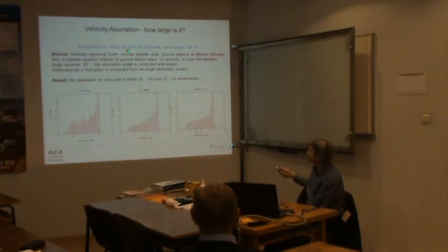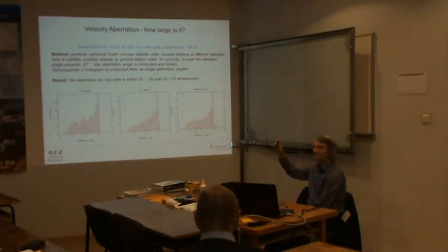We assume an orbit of a typical remote sensing satellite, 620 kilometers, with an inclination bigger than 90 degrees, 98.4, let's say between 97.8 and 98.5 is a very popular inclination. This is the so-called sun synchronous orbit. This is an orbit where the satellite cruises over your ground station always at the same local time of the ascending node.